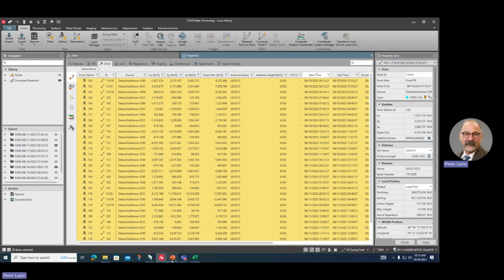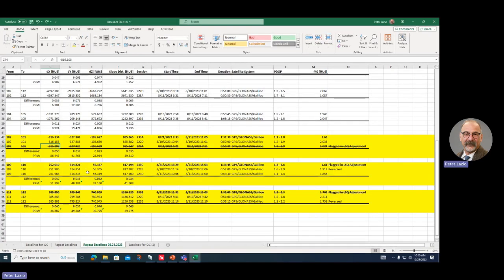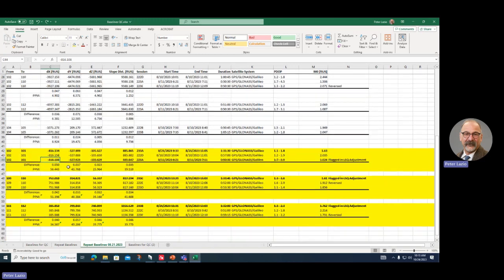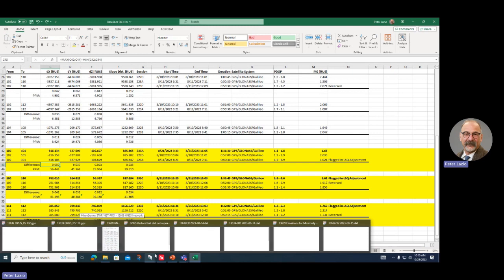It would be really hard. I've done a lot of baseline processing. It'd be really hard to tease out from 500s to 18,000s. Yeah, you can't make them be what they're not. Mostly what you would do is try to raise the processing mask. You might try to take out individual satellites. I would try to take out entire constellations before I would try to take out individual satellites.